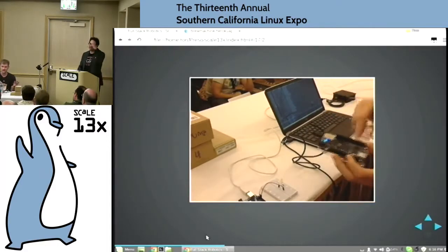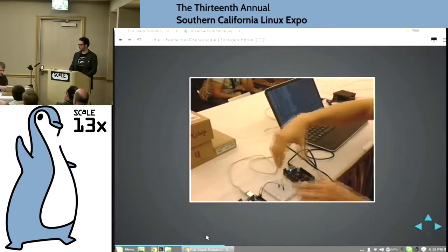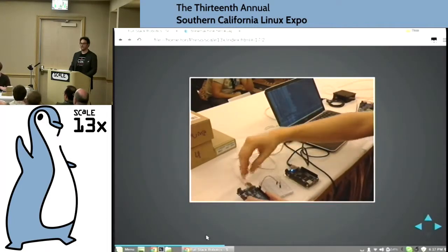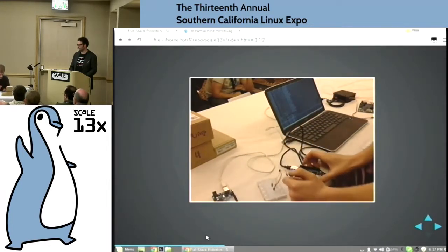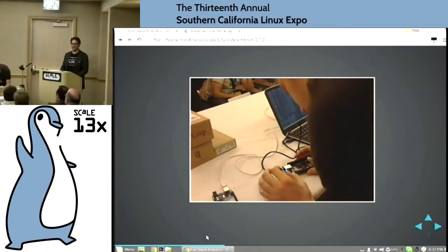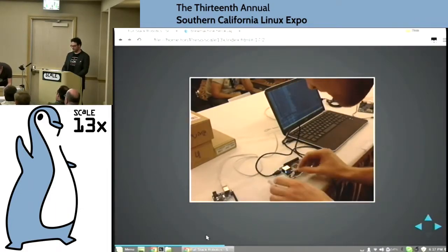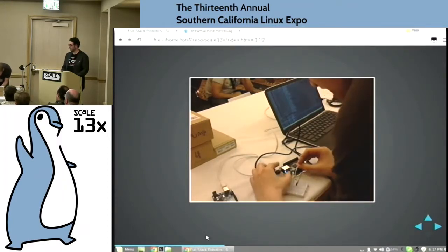So I'm actually SSH'd into this Linux computer from my laptop. Just to show you how there's no trickery here, the same exact circuit that we used for the Arduino, I'm going to plug that directly into this BeagleBone Black. This is where the labeling thing is really useful. This is going to go into P9 12. First we're going to put in our ground in here, and then we're going to do a little counting.